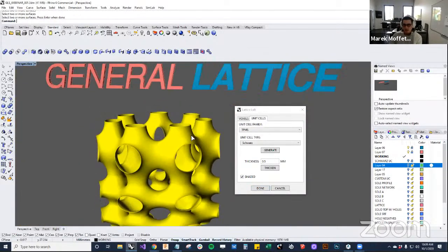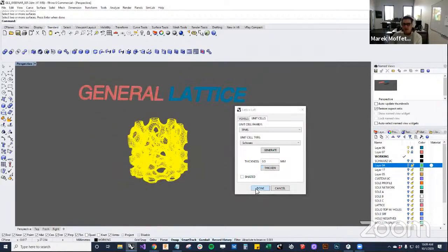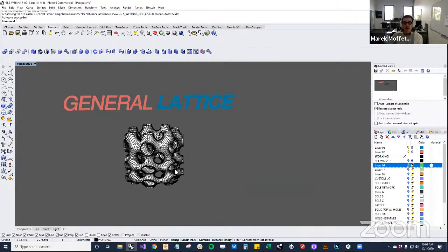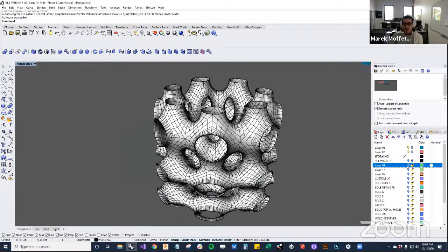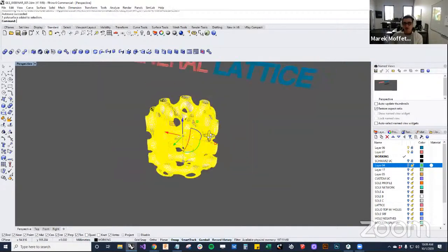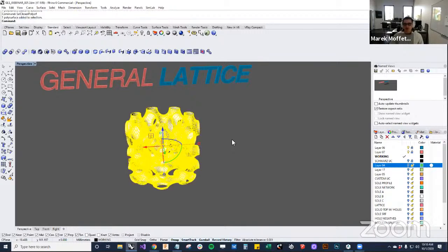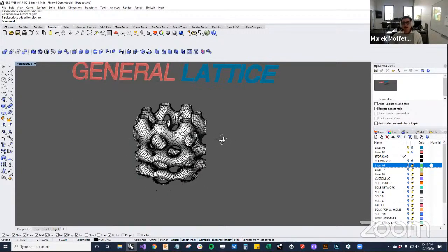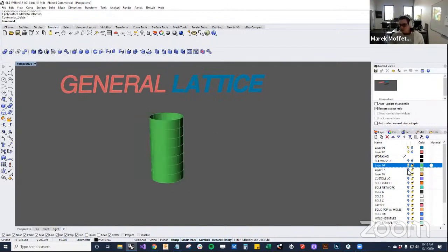Very thin. I actually want to keep that like that. And so I'll hit done. And when you hit done, the structure will be baked or set to the Rhino viewport. And now we have a single closed polysurface here that we can manipulate and do our Booleans and what have you. And we'll just make sure it's a closed polysurface, and it is. So that was a quick example of how to use just 2 surfaces.